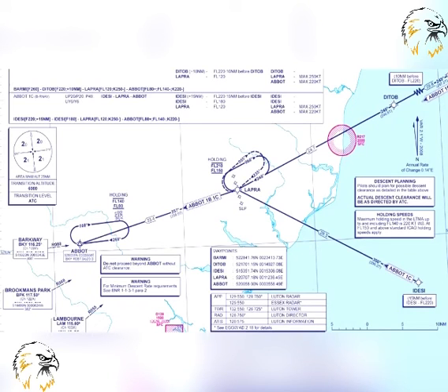You must not forget that there are several factors that affect the accuracy of RNAV systems. To remind you, these are ground station tolerance, airborne receiving equipment tolerance, flight technical tolerance, system computational tolerance, and distance from the reference tolerance.